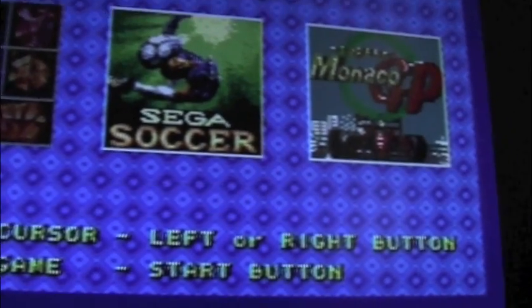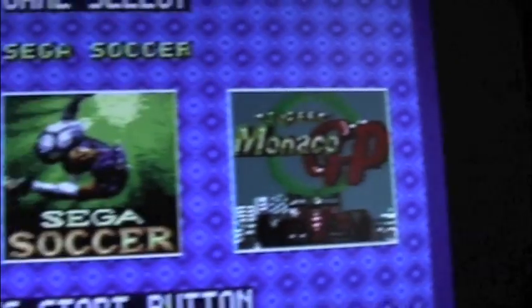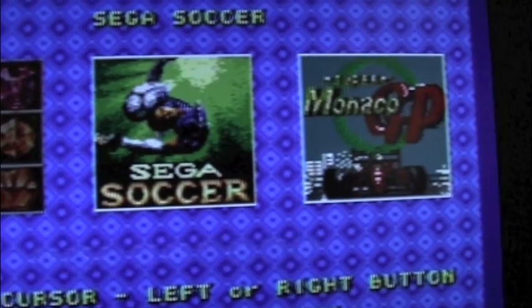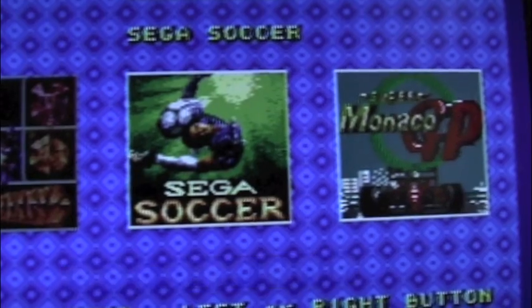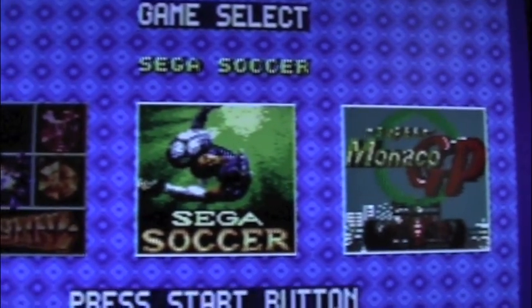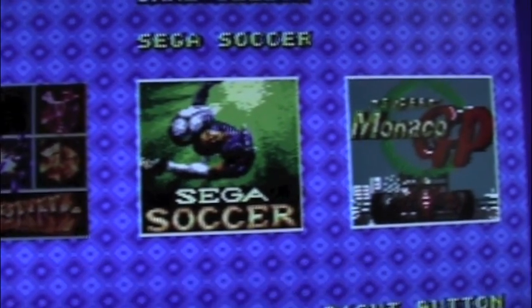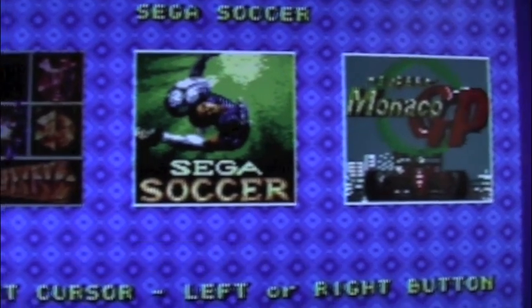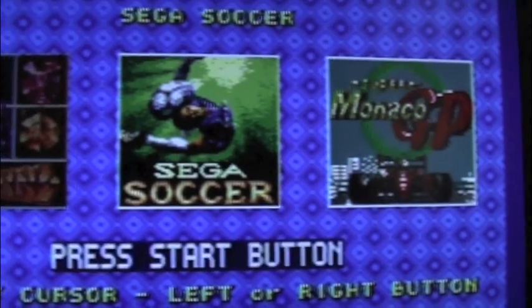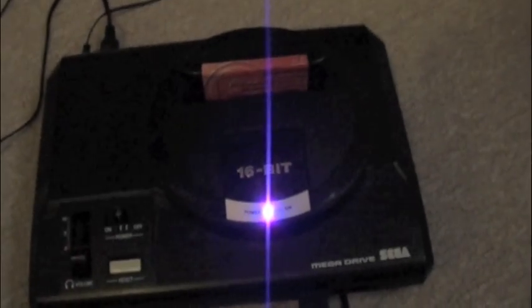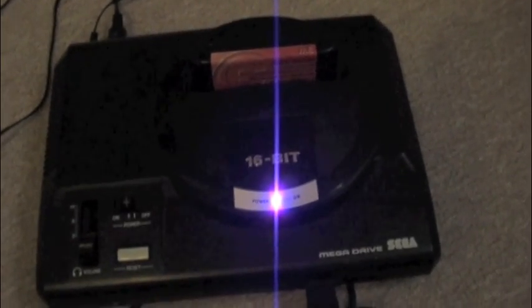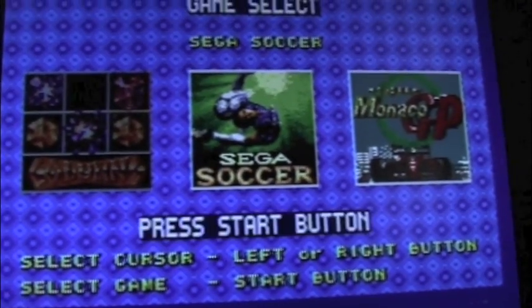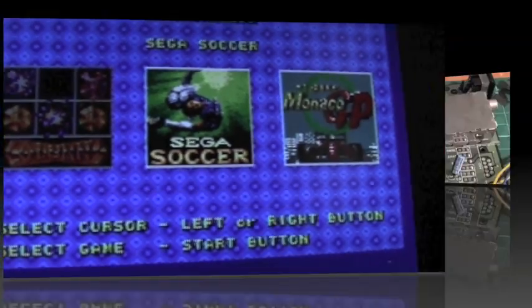Now the reason why it does this is because the 50-60 Hz isn't quite correct. To keep the costs down, Sega put the switches in and just bridged things, and the main chip oscillator was set so that it's divided by 1512. Anyway, it's very complicated. Because this is the Megadrive 1, there's a guide on Monkey's website which will enable a PAL 60 signal to be sent out. So I'm going to do that.